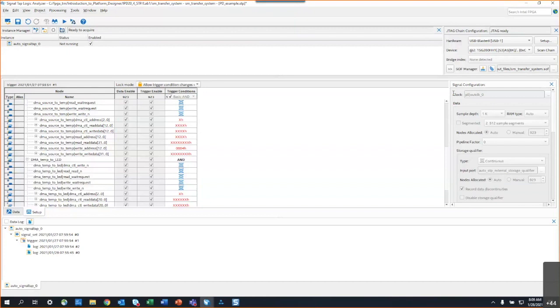What else we got, Susanna? Okay, so another question is they're wondering if SignalTap works like Trace, if it's real time, or how exactly does that work? Good question. So SignalTap is meant to be able to capture high-speed signaling that you could never see when you're seeing it run in real time. So SignalTap is not a direct trace.